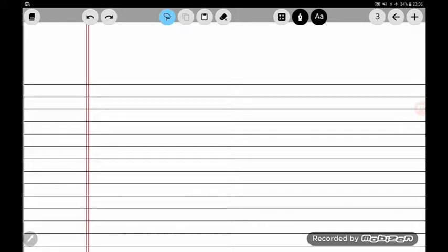These equations are given as m1 x2 double dot plus b1 x2 dot plus (k1 plus k2) times x2, and that's equal to k1 x1 plus k2 x3.